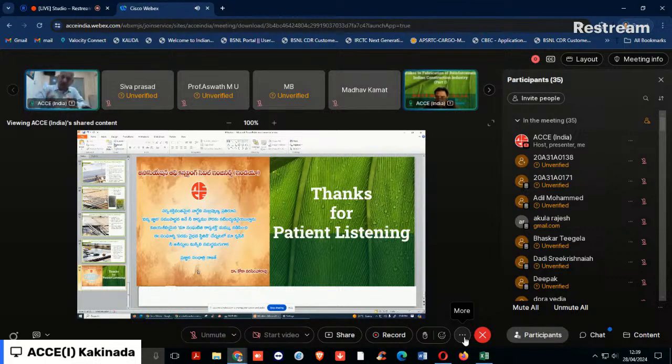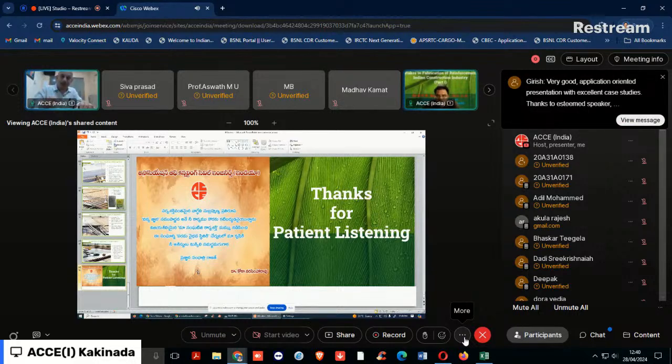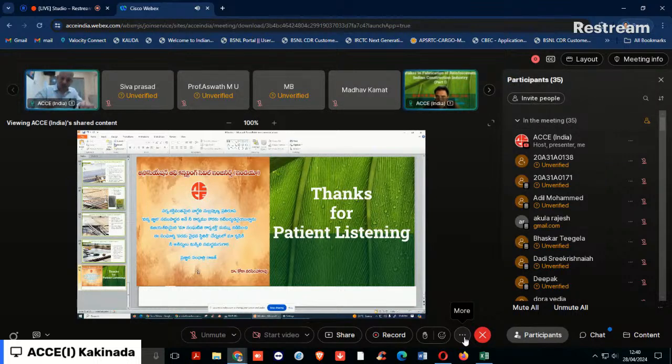Practically, that is the dowel action taking place in the RCC beam element or the column element when there is diagonal shear action. For the diagonal shear action, we have to consider the shear capacity of the bar in one-way shear. Shear failure in a beam is brittle in nature. We want to eliminate that brittle failure and the catastrophic failures of the shear reinforcement.